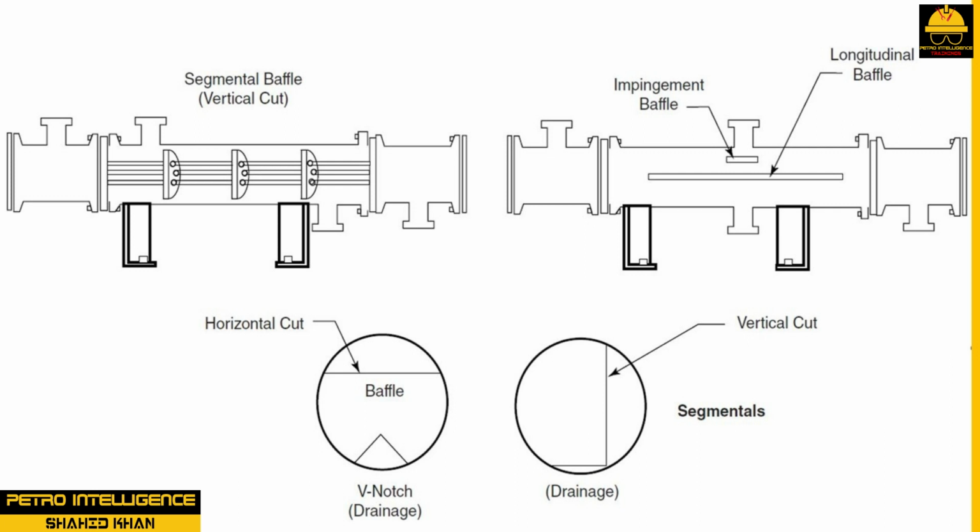Single-pass exchangers do not need a baffle in the inlet or return head. Multi-pass exchangers requiring two passes will have a single baffle in the inlet channel head. A variety of baffle arrangements are available. Cost goes up with each pass. Additional passes are often needed to provide adequate fluid velocities to prevent fouling, internal buildup of material, and to control heat transfer.